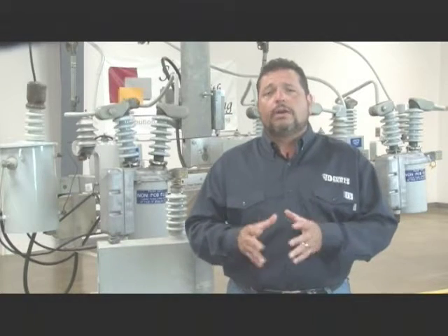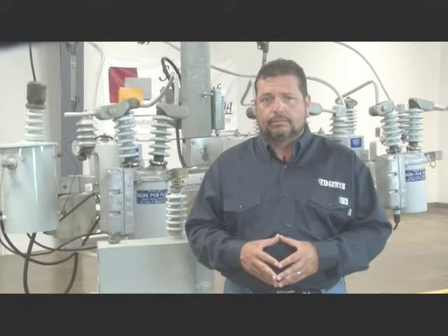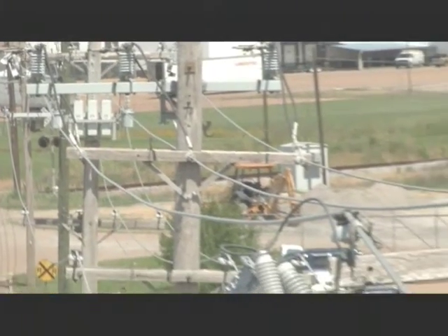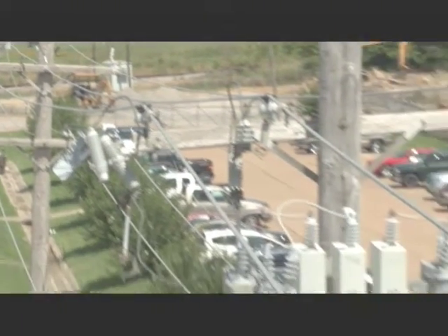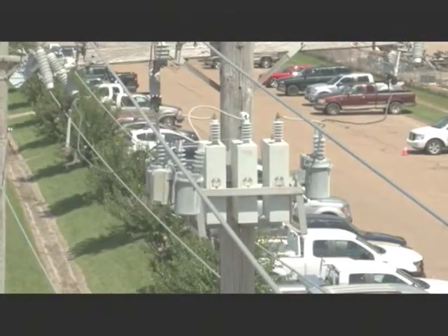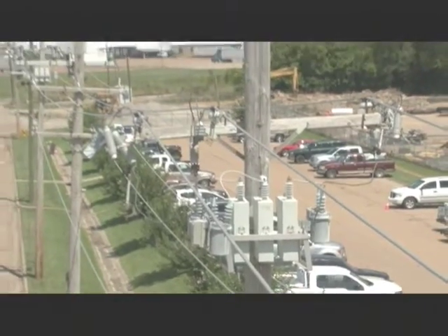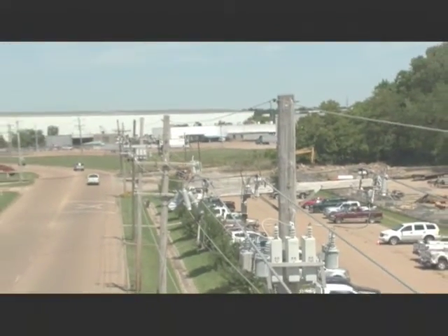Now that we've identified some of the basic parts of a capacitor bank, we'll follow along as a line worker makes a visual inspection of a three-phase capacitor bank. It's important to realize that special care must be taken when working around capacitors. Even when the circuit is de-energized, the capacitors may still hold a charge. Although the bleeder resistors are designed to reduce any stored charge to 50 volts or less within 5 minutes, it is possible under some conditions that the resistors will not do their job. Capacitors should always be treated as fully charged until they've been de-energized, shorted, and grounded.